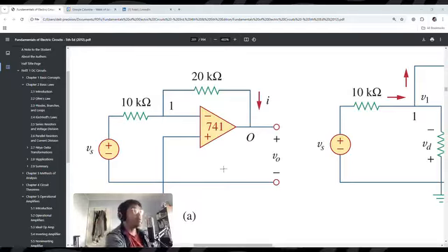That is because we are going into the inverting input of the op amp rather than the non-inverting, and the non-inverting is tied to ground. So when we send any AC signal into the inverting input, at the output we expect it to be flipped 180 degrees.